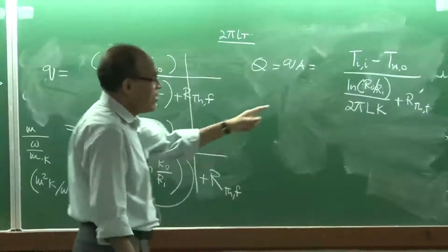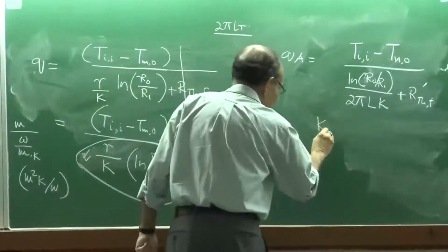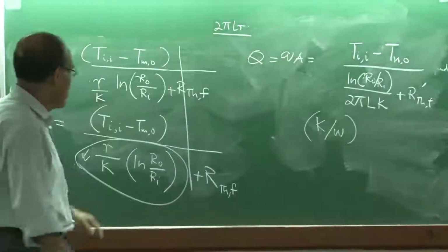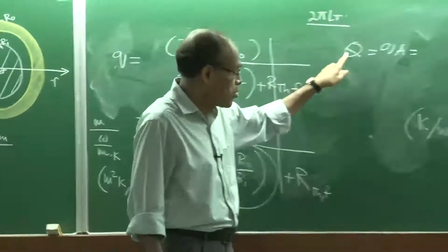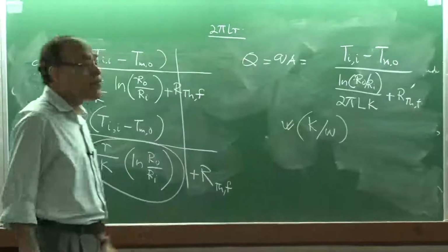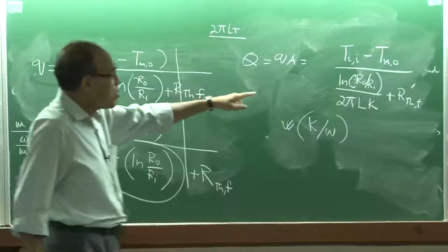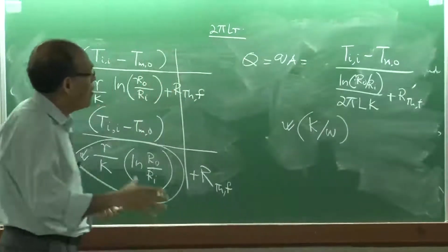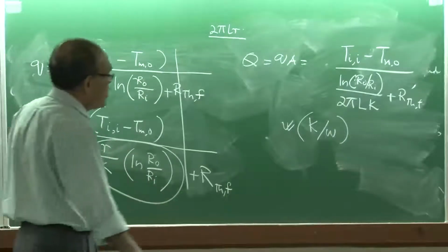In this case, the thermal resistance will have a unit of Kelvin per watt. So you have two different conventions. Some people write resistance with respect to flux, some people write it with respect to the net flow, but I think this is more appropriate, because it is represented by considering similarity with the current flow in an electrical circuit.